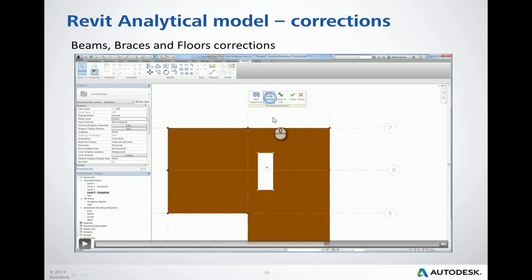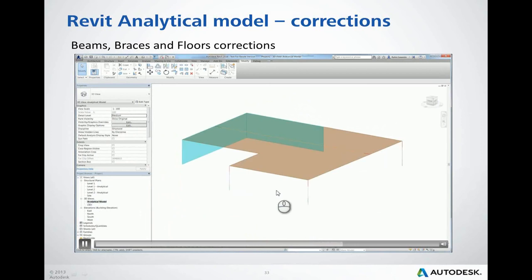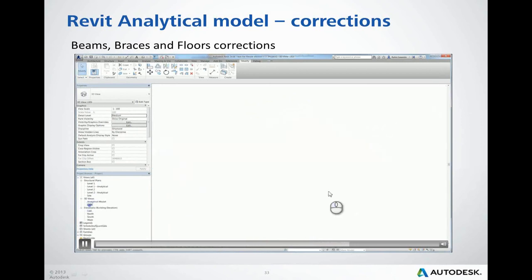So as shown previously, the geometry of the opening is taken into account from the boundary lines of the real slab geometry, but disabling or enabling can be activated in analytical adjust. So as you may see now, the opening is disabled in analytical mode, but we can still see it in the real model.